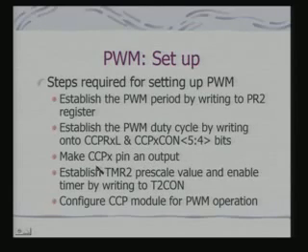We have to make the CCPx pin an output. We need to establish the TMR2 prescale value and enable the timer by writing onto T2CON. In fact, all the timers have an enable bit which we have to set to enable the timer, and then configure your CCP module for PWM operation.